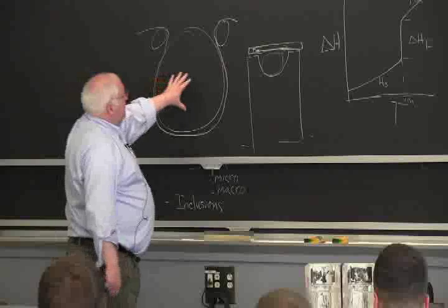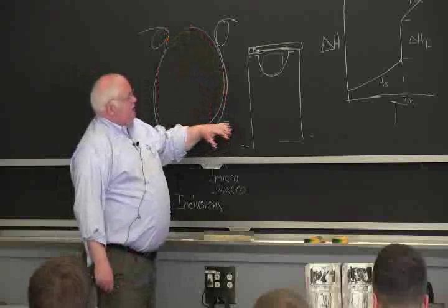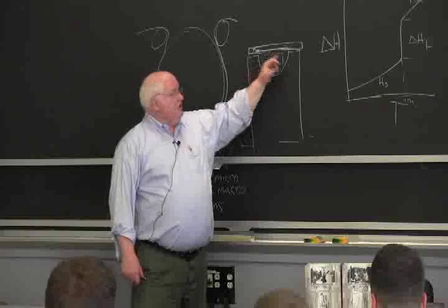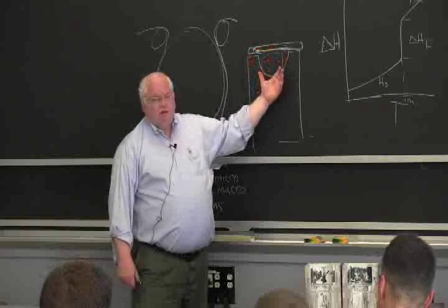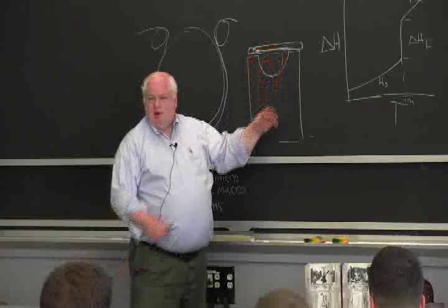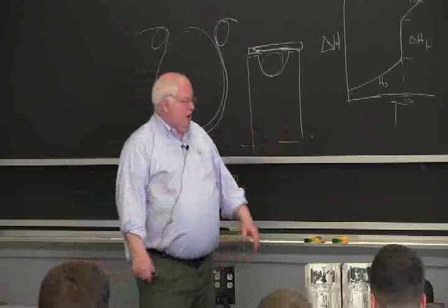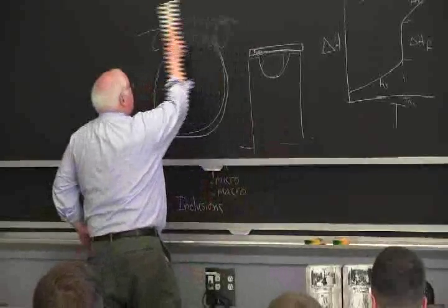But in any case, this is a Southwire process, 6-foot diameter wheel, turning out kind of 2.5-inch diameter. It's actually not a circle. It's this, you know, half moon shape or whatever. But you're going to go through and roll it into a rod, and then you're going to draw it into wire. It'll produce a lot of copper for the world.